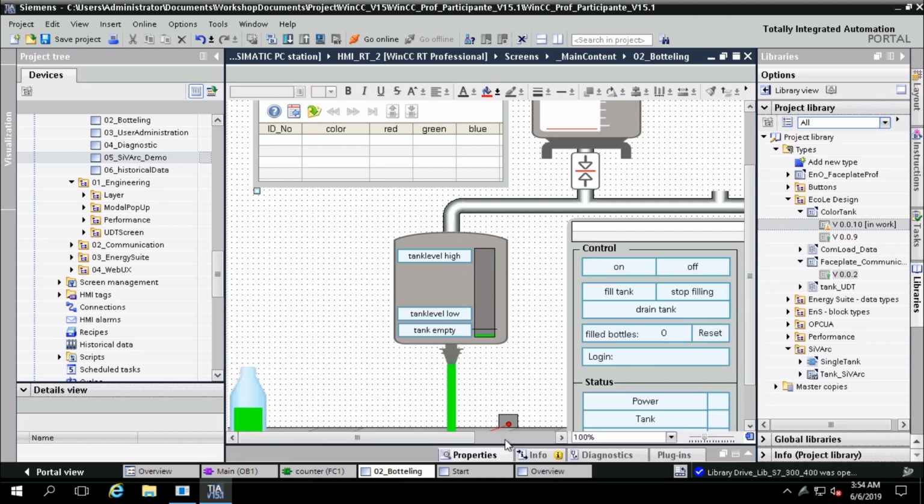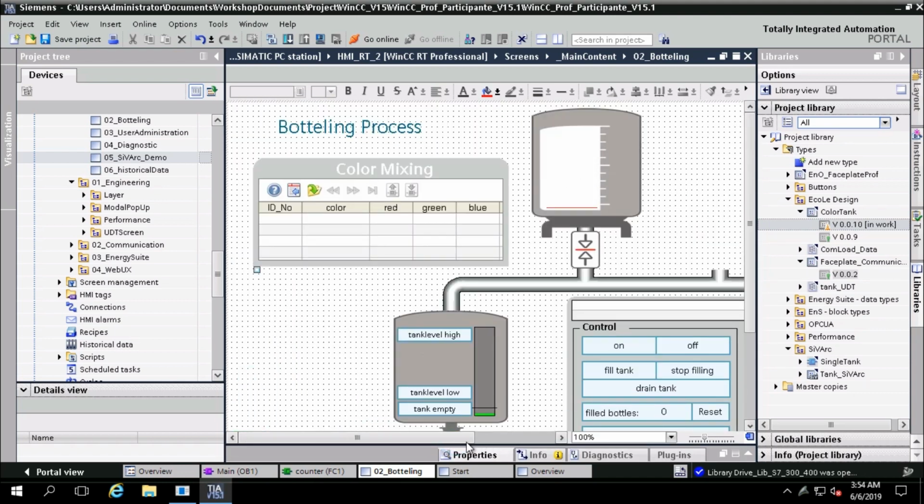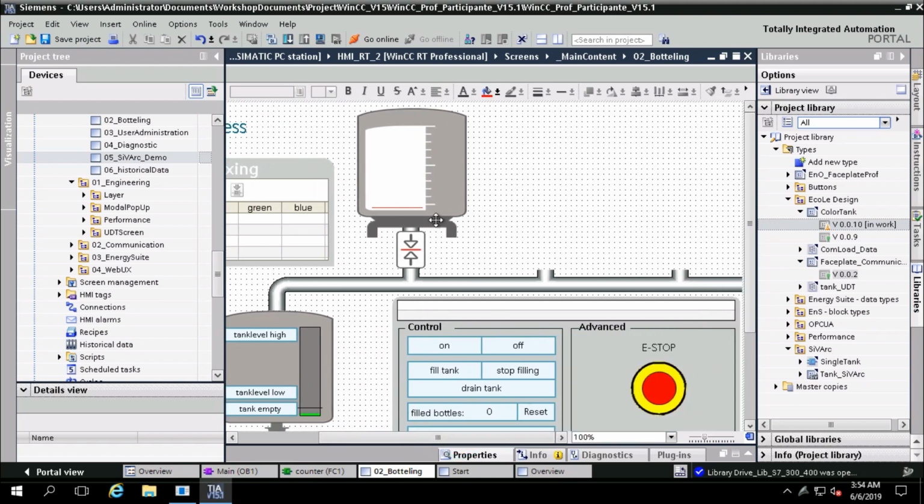And in this interface tab, when I open this one up, I can also see the same list I saw in the faceplate or in the library management. These are the properties I put to the outside in order to link them to the tag. So I also see and find my valve status here again. And I can now say in the dynamization column, connect. Up here. Oh yeah, that's modified, sorry. So I need to use this one here because if I modify it, I can also create a function list or a script for that, but I just want to create the tag. Or I can also create a VB script or a C script in that case, but I'm okay with the tag. So I create an HMI tag link and choose my tag I want to use here.